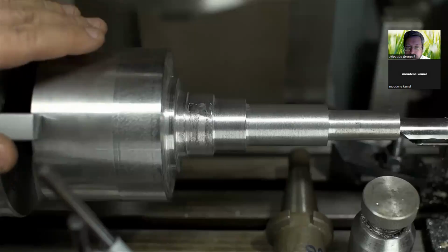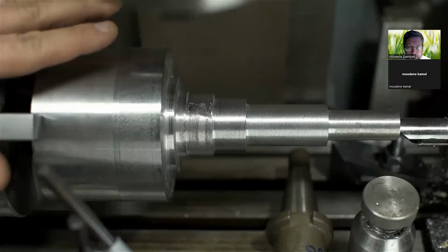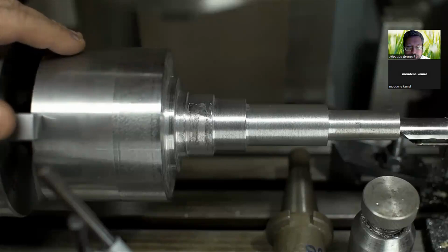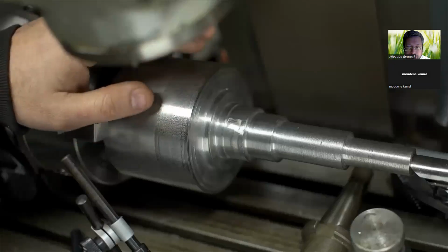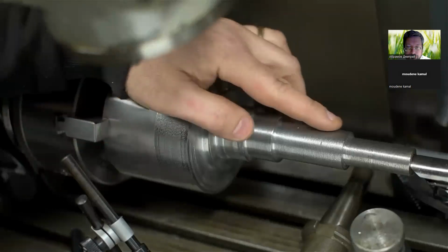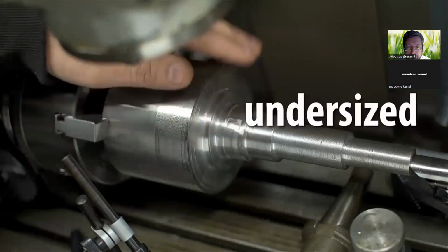Best I could do is get this thing centered to within about 1.5 thou. That's total runout. After 20 minutes, I've given up and am calling that close enough. According to the good book, if I do the rest of this right, I should still be in tolerance. That and their finished OD, where the spline goes, is a bit undersized.